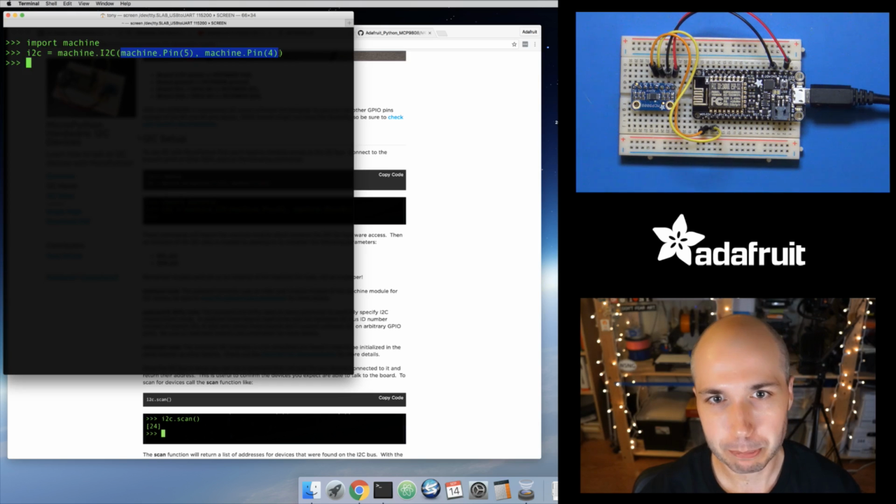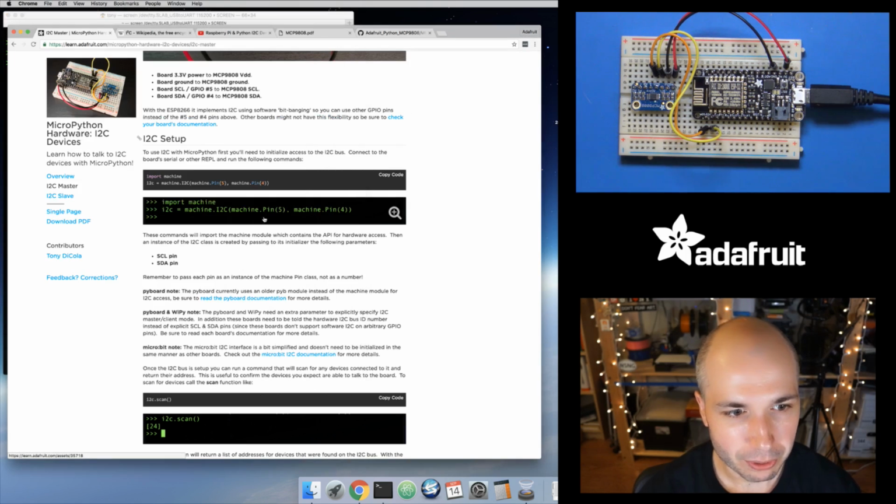There's a very specific clock line and data line for that hardware I2C interface. So when in doubt, check the board documentation. The quick reference for all of the boards usually has a pinout description that shows all the pins, and you should look for the I2C clock and data line, and that should help you find out which ones to connect to. So okay, at that point then,